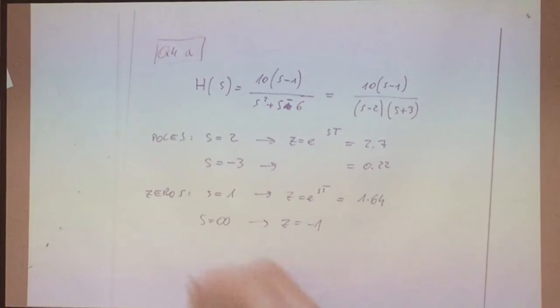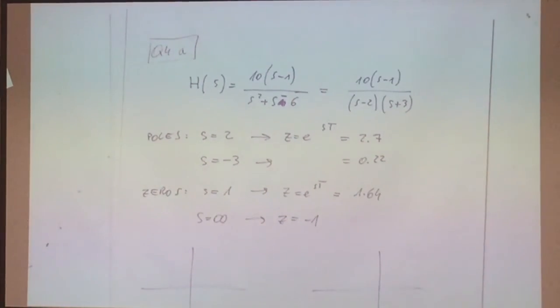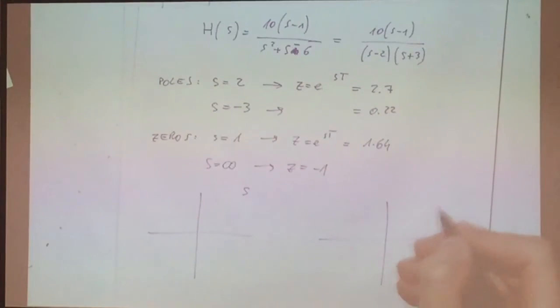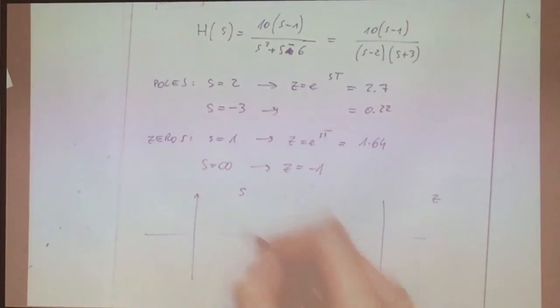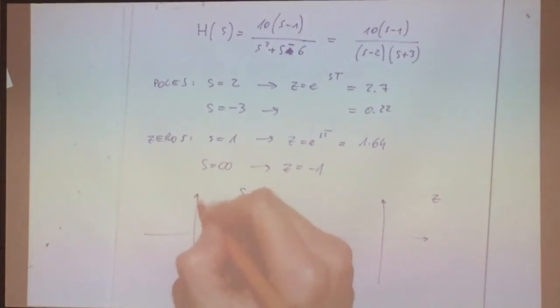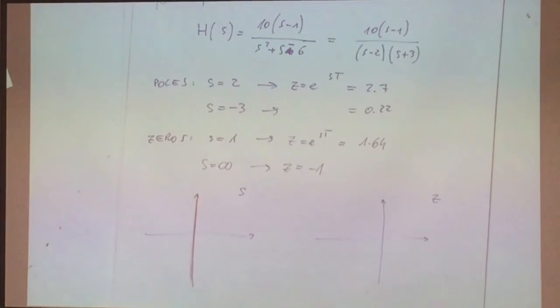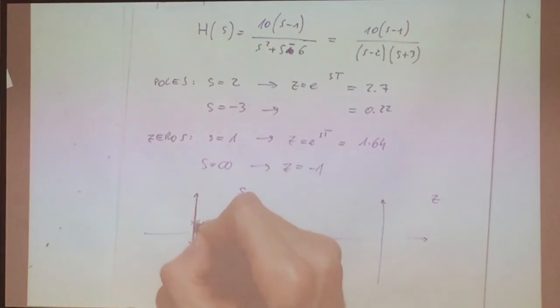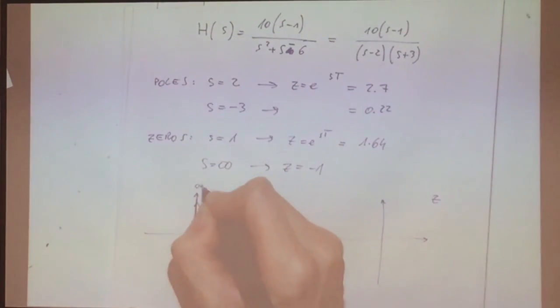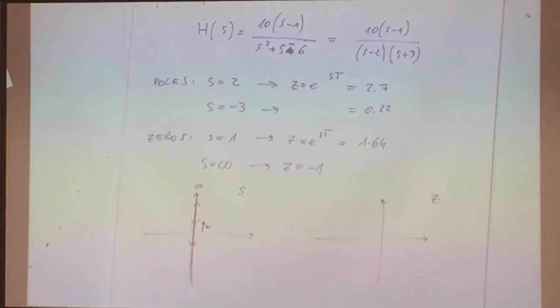Well, to understand, we need again to draw the two complex planes, the s plane and the z plane, and see what is going on at infinity. Imagine to consider again the imaginary axis here on the s plane, and imagine to have a pole, or a couple of complex conjugate poles, with a certain frequency omega, but this frequency increases up to very high frequencies, up to infinity. So you imagine to move the pole here until you get to infinity on the imaginary axis.